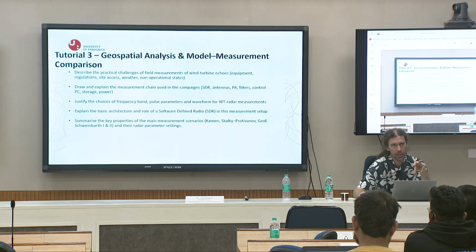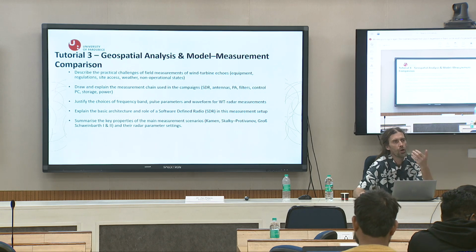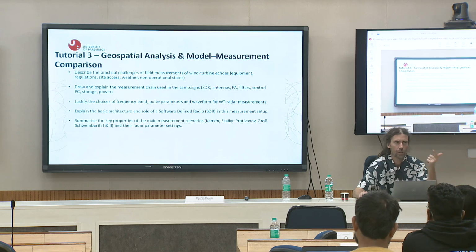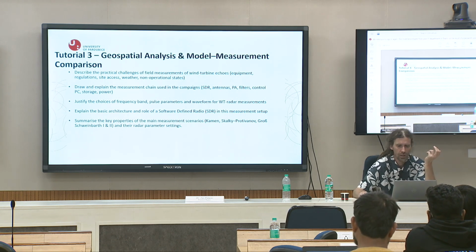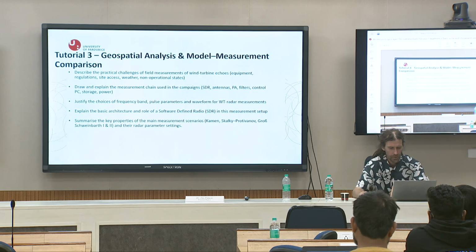Directly processing on the SDR, so you will need to program the FPGA part that an SDR contains, or you just make a raw measurement of IQ data, and then you need to do post-processing somewhere, again MATLAB, Octave, and so on and so on. It is your choice. It is nothing mandatory.